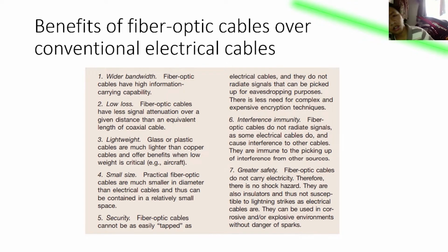Okay, so in further understanding the concept of fiber optics, we should ask ourselves why it is better than conventional electric cables. First and foremost is the wider bandwidth. It has the capability to transfer higher bandwidth, which in turn means a higher data rate. Okay, low loss. Fiber optic cables have less signal attenuation over a given distance than an equivalent length of coaxial cable.